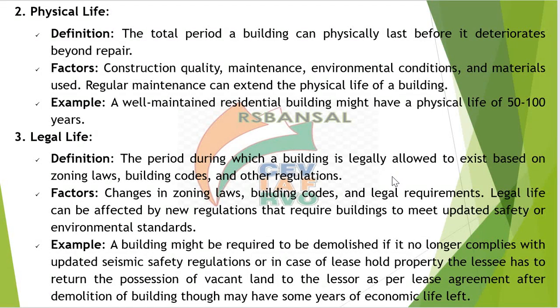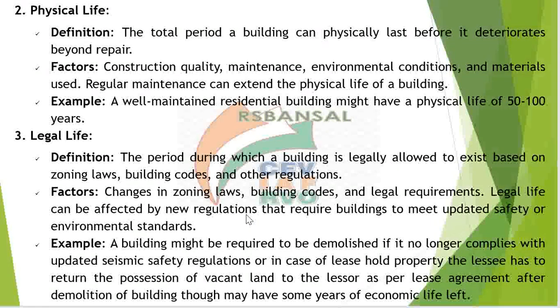So, though the building may still have certain life left at the end of 30 years, as per the lease agreement he has to demolish that building and return the vacant open land to the lessor. So we say that its legal life has come to an end. This is legal life, meaning a time beyond which you cannot use it legally as per the building codes, zoning laws, or other legal requirements.